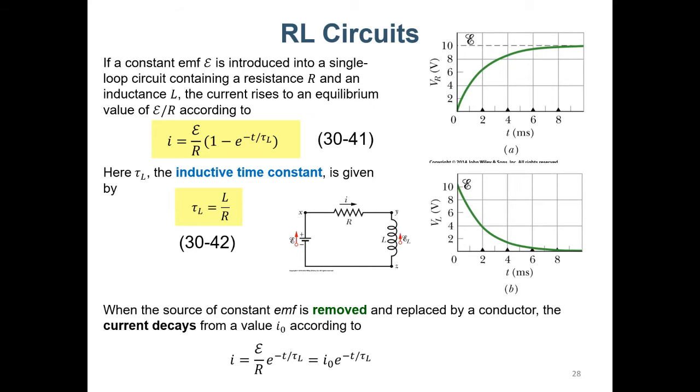We find that I at 0 plus should be E over R, which is the final value from the previous case, which should equal A exponential to minus R over L T, and substituting 0 here, A times 1 is A. So finally, for that case, I should be E over R exponential to minus R over L T, which is this one.